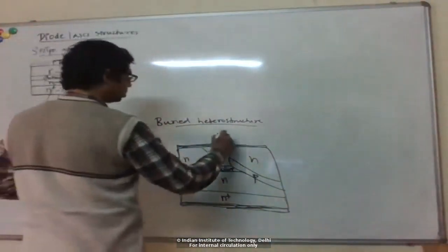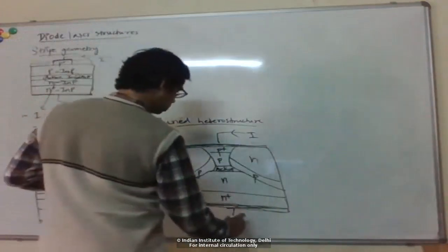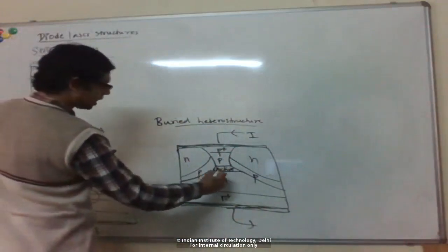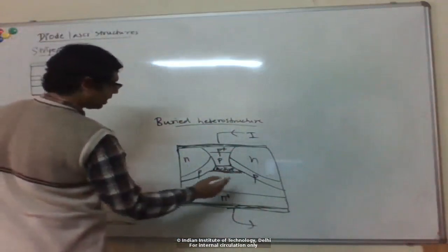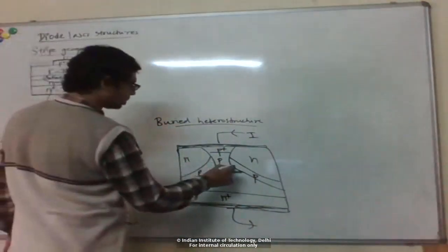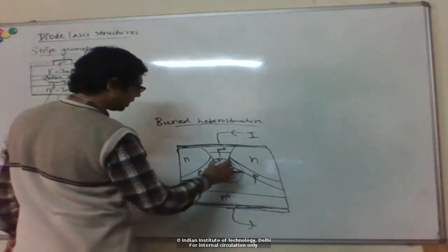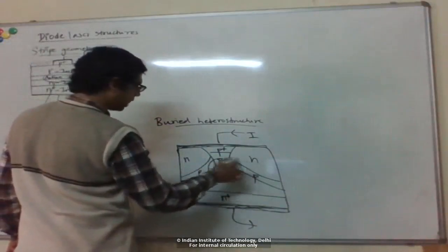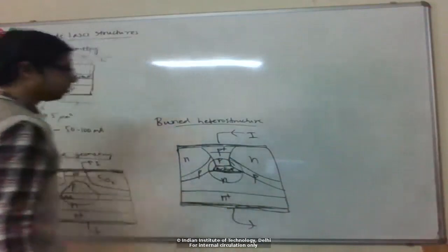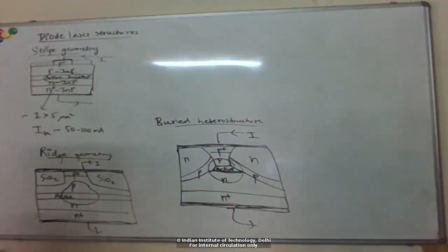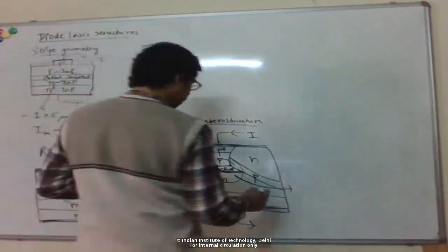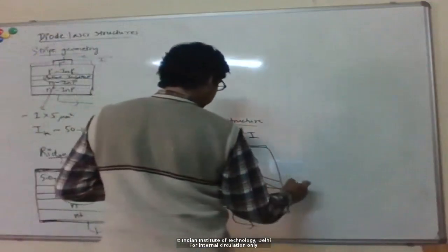So basically you etch into the active region. You can see now the active region is the small region here, not extending to the whole width of the device. Of course, the light is only generated in the active region, and also you're getting lateral confinement here. Like in the vertical direction, you're also getting lateral confinement in the horizontal direction. So the mode becomes close to circular, and the ellipticity becomes less than 2.